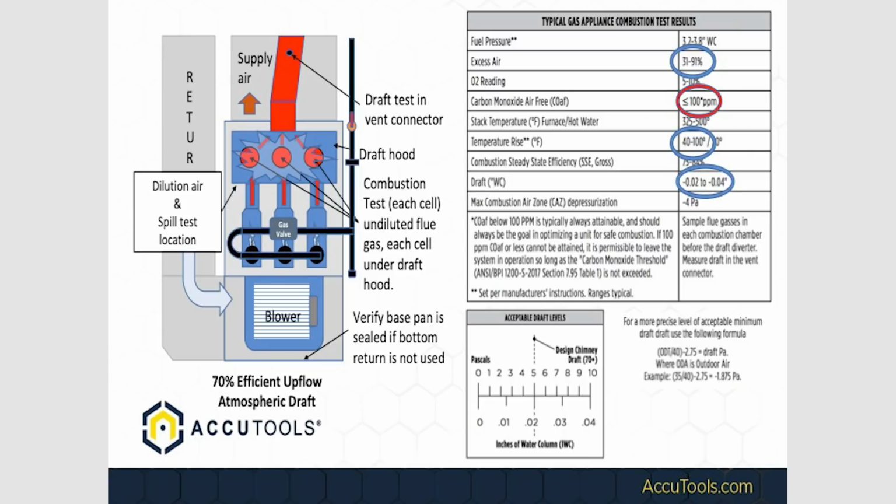This is again that CO poisoning Bill and I ran across years ago. 90 plus furnace. They actually condemned it. It was a comfort maker furnace, cracked heat exchanger, reasonable standard of care. The guy shut the appliance off, said, "Lady, you got a cracked furnace. Let me get a new furnace out here and we'll get it put in." Take the old furnace out, put the new furnace in.